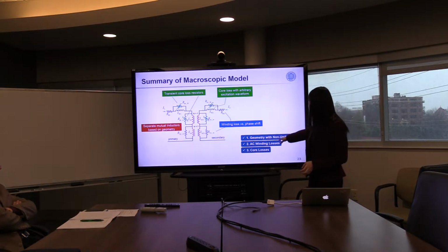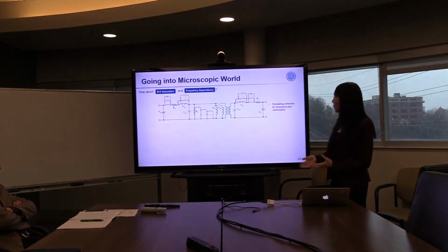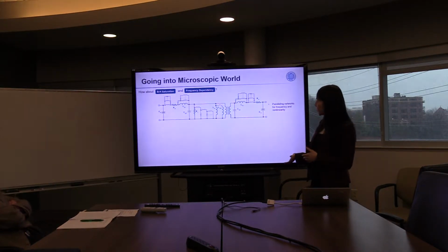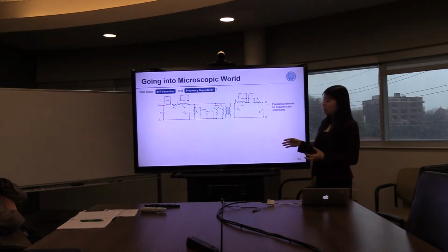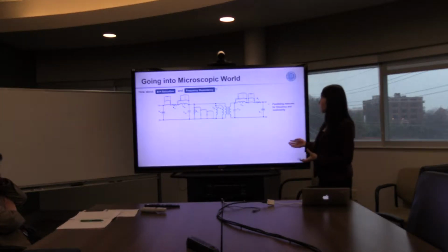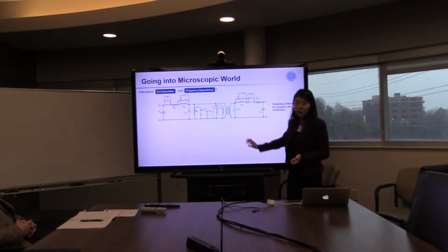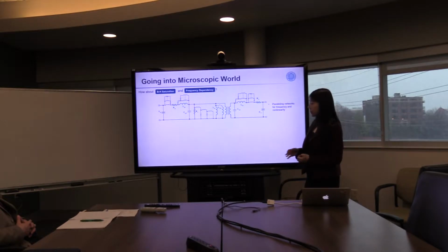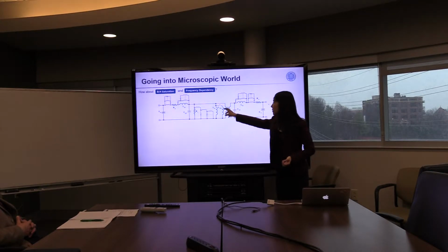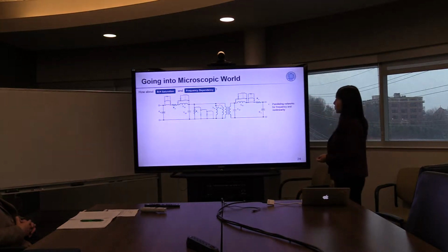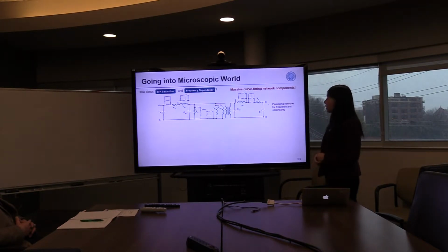This helps us to deal with the three challenges we mentioned earlier. Then how about the other challenges like saturation and the frequency dependency? There are actually also existing methods in power electronics where we can just add these paralleling networks to include the frequency dependency, and we can also add a switch there representing when the inductor saturates, that is the saturated value of your inductor. But this requires massive curve fitting networks.